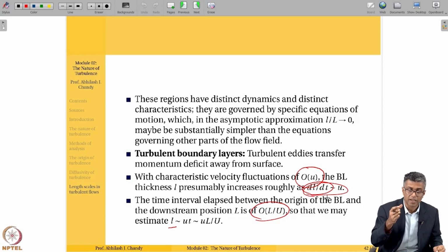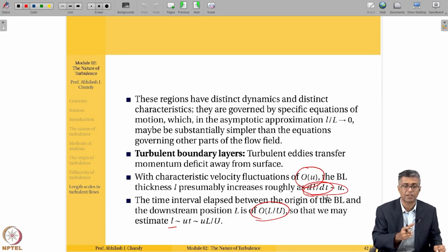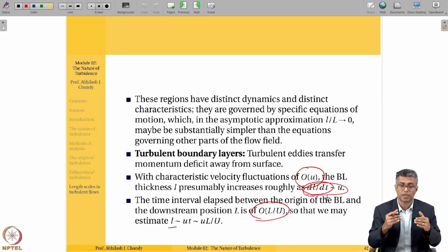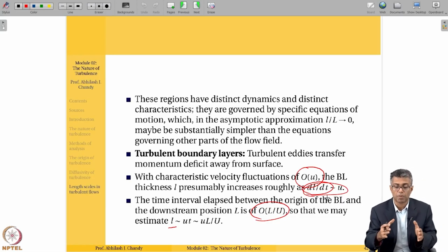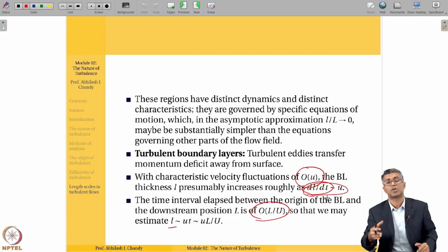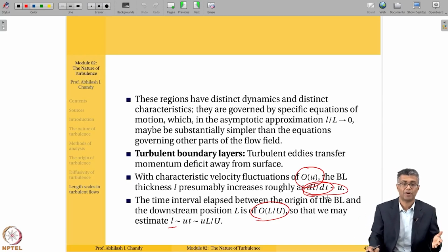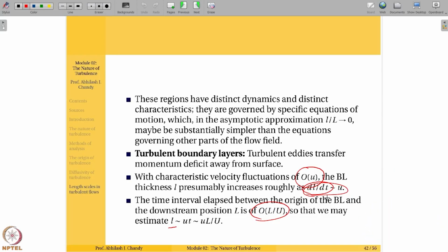We have taken the diffusive length scale and the convective length scale and tried to come up with relationships based on the ratios of these two length scales, and even better, we related these ratios to the drag coefficient both in laminar flow and turbulent flow.